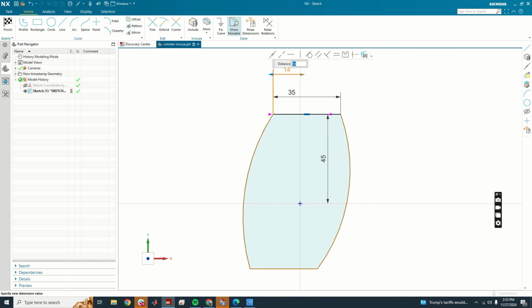And the reason was, even though I had it snapped to the center point previously, NX left that as a slightly flexible constraint. So if it was defined in a different way, then it says, okay, I can break this constraint in order to meet this new dimension. Now, this is actually a bad thing, because if you set up your sketch in a specific way using constraints the way you want them to be, and then as you're going back and forth and editing different sketches in order to change things, it could conceivably delete some of the constraints that you previously set up and that could have been important to you.